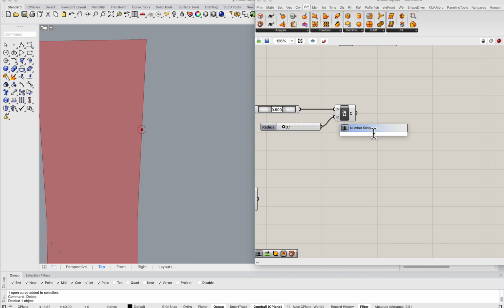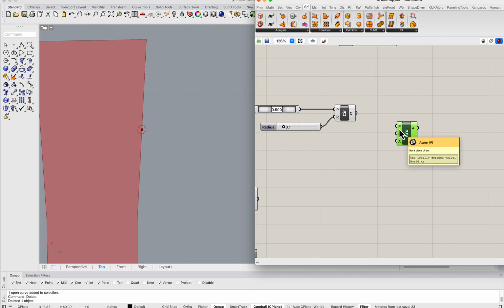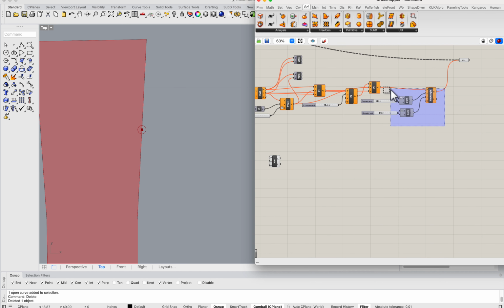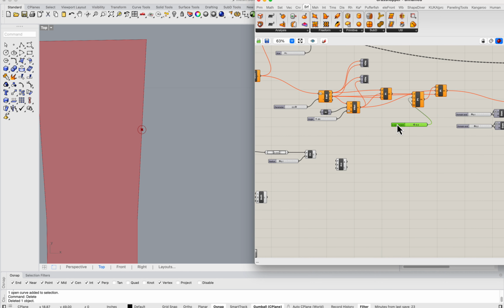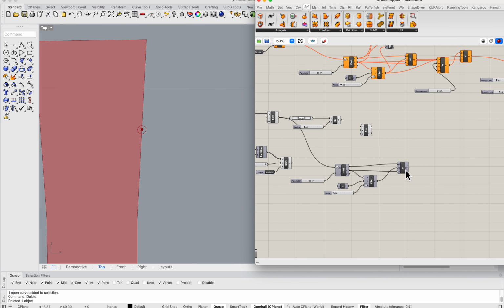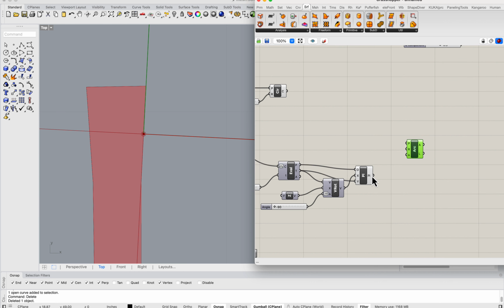And for that, we're going to use the arc function. And the arc would also require a base plane for construction. So this might actually come in handy here, right? We can actually use our previous construction. So if I just make a copy of this and then use this edge construction and look at this plane, that already gives me a nice orientation. And this arc can use this plane, but it will also require a radius and an angle domain.